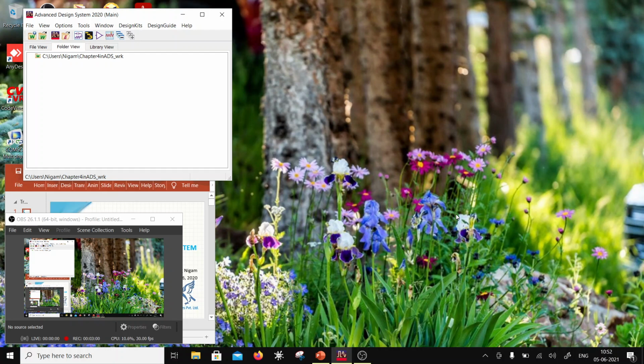So we are solving a linear system for a given frequency component, and then we are combining them. Because the principle of superposition will work here, since we are doing a linear approximation for that frequency, we will be able to combine the outputs to result in the final nonlinear output. So this is how harmonic balance works. So that's what we are going to do.